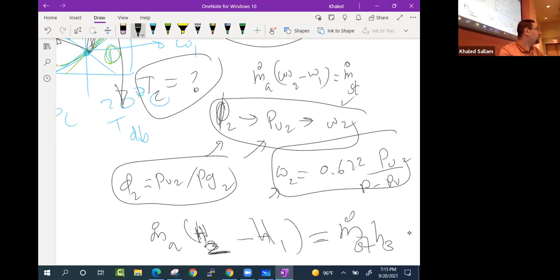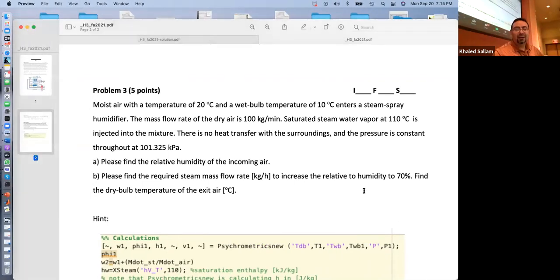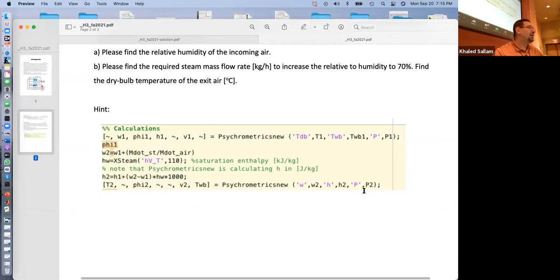It requires some kind of iteration because the way things are, you need a steam table. To get P sat 2, you need T2. Then you go to the steam table, get the P vapor 2. And because it's a little bit hard, right? And I'm such a nice person, nice professor. I am. What did I do? What is this?